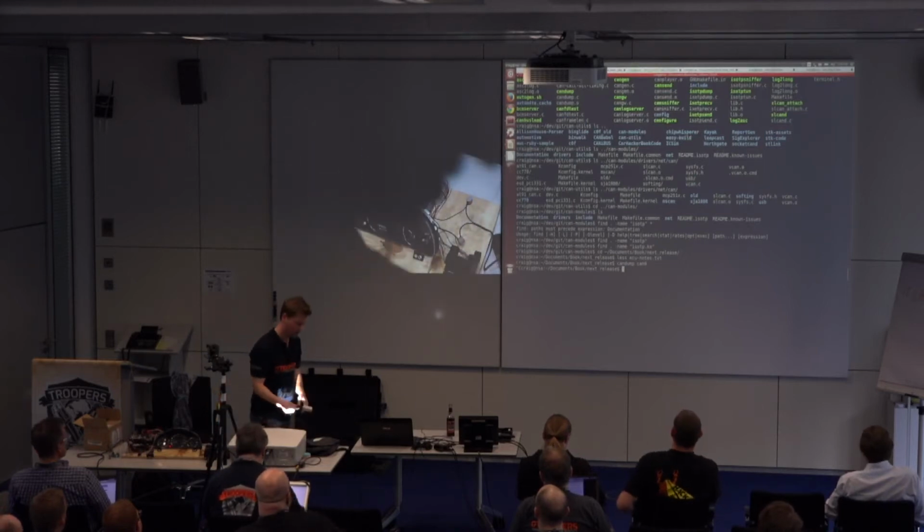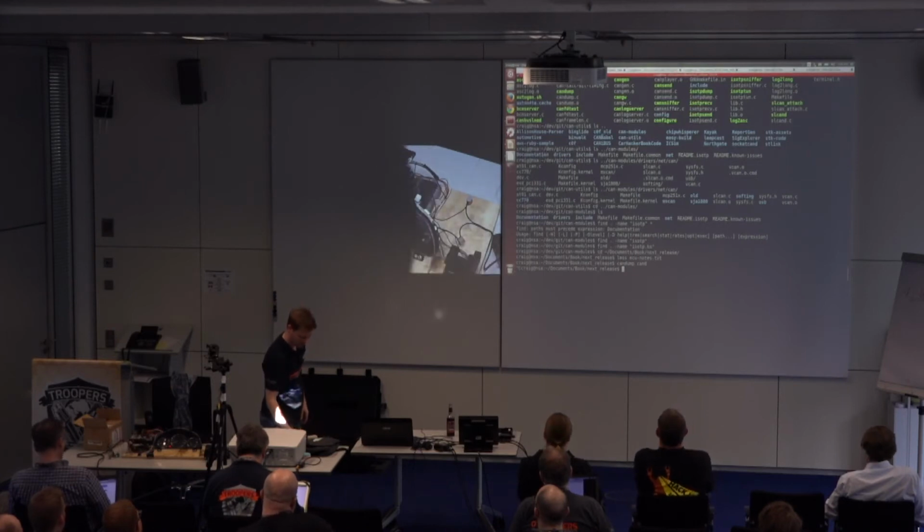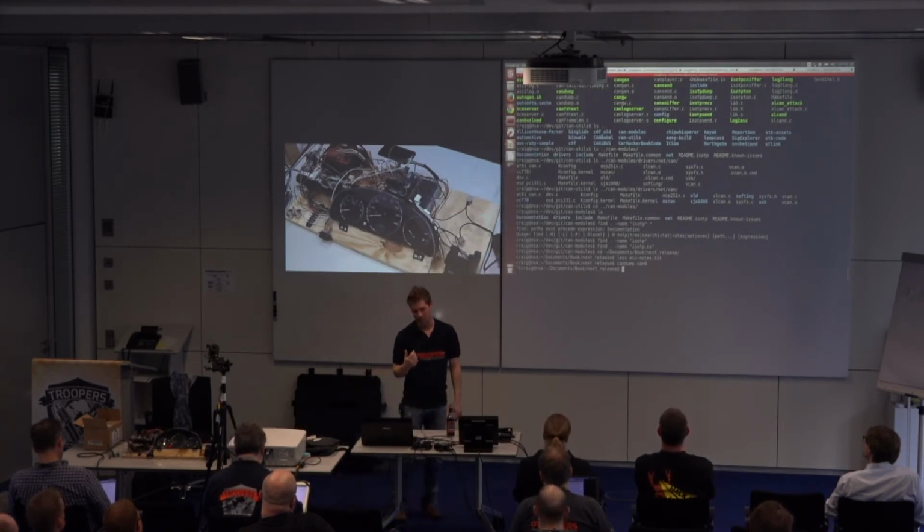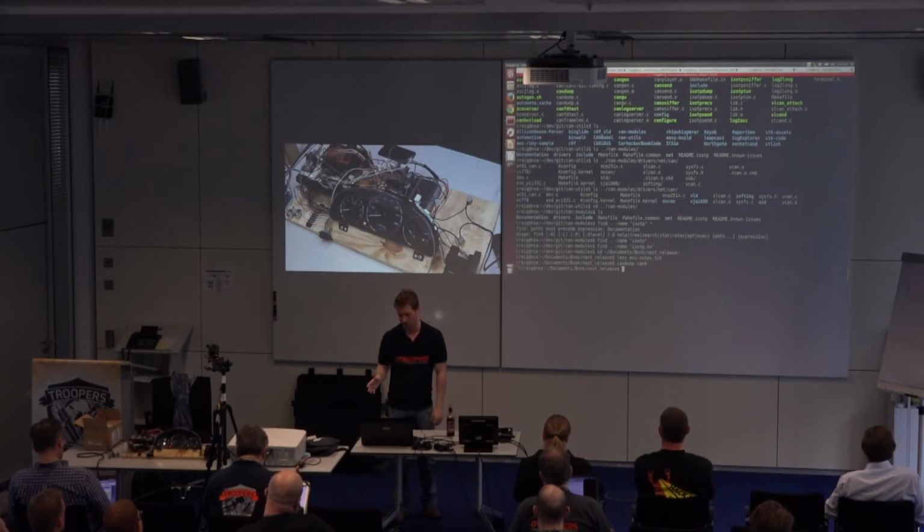It's not open source. It's from 8 devices, but it is pretty high speed for CAN. The nice thing about it is it shows up as a CAN device. Most show up as a serial device and have this extra translation to it. So this one is just raw USB. It does CAN, so you can directly talk to it. I haven't really had many problems with the serial ones either.